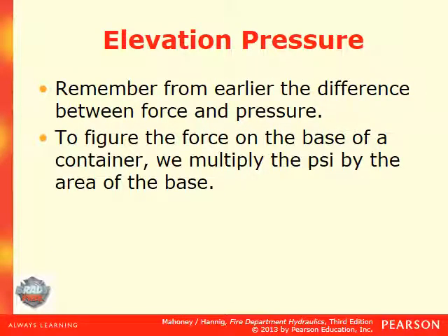All right, before we move on to the next set of problems, some things to remember. Remember from earlier the difference between force and pressure. To figure the force on the base of a container, we multiply the PSI by the area of the base. So our formula is this: force equals pressure, that's in PSI, times area of the container.